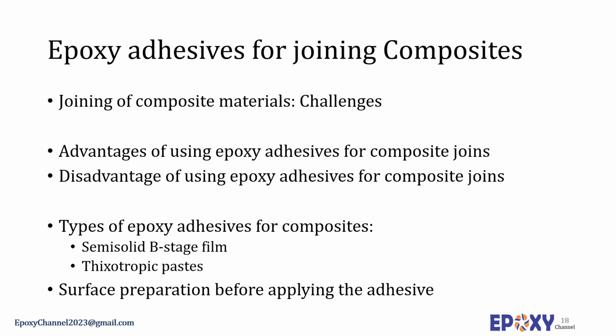A significant advantage of using adhesives for composite joining is that adhesive bonding does not require the composite to be drilled or machined, processes which drastically weaken the composites. A cut edge also allows moisture wick-up and further weakens the structure. The three adhesives most often used to bond composites are epoxies, acrylics, and urethanes. Due to the similarities in chemical and physical properties, epoxies are especially reliable when used with epoxy-based composites.